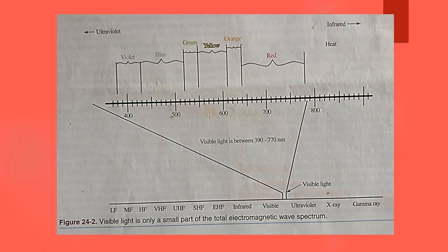Most fiber optic systems use infrared wavelengths between 850 and 1500 nanometers. At these wavelengths, there is less loss of signal. A typical LED has a wavelength that is between 800 and 900 nanometers, or 1250 to 1350 nanometers.